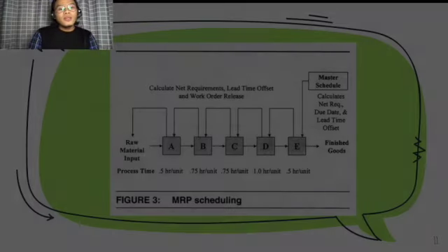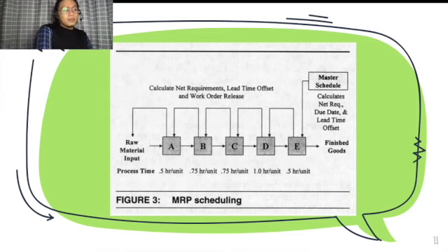Okay, so this is the flow of the MRP scheduling based on the simple model earlier. As you can see in here, this is the fundamental logic of the MRP system and how it schedules the five processes. To begin, it is important to realize that an MRP system will identify a fixed lead time for each process. This lead time includes the move time and the WIP, or work in progress, wait time for each process. Thus, the lead time for process E might be about 1 day.